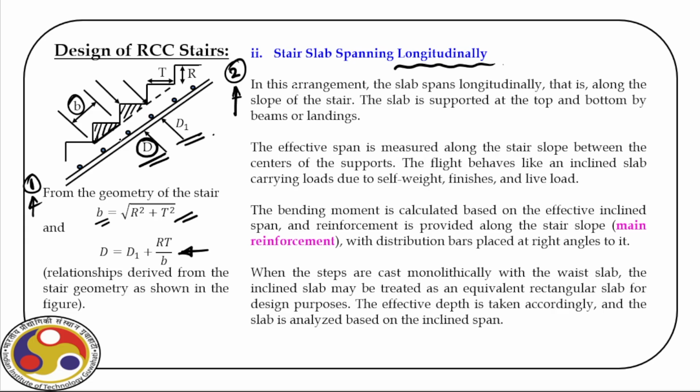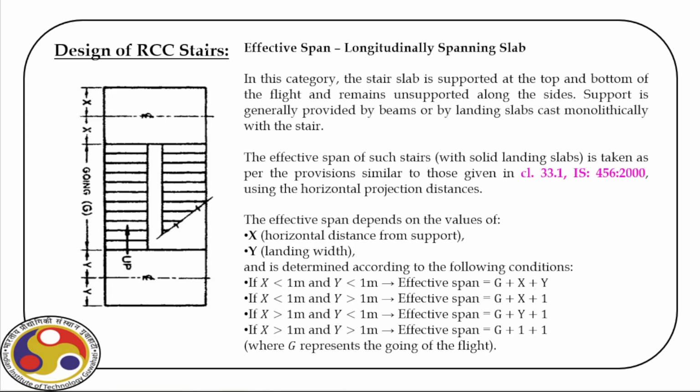So before we design this slab, the first thing that we have to keep in mind is the geometric design, and from that geometric design we have to find out the net load acting on the slab. The moment we do that, we can easily design this as a beam supported between the points 1 and 2. However, this slab is obviously inclined, so accordingly we have to take the load in our estimation appropriately.